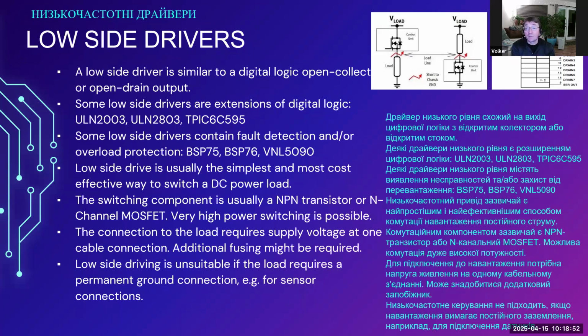This means that one end of the load is connected to the supply voltage. This might have effects on the cabling that you're using. I will talk about that. This is generally the easiest way of switching a load. Low side driving is not the intuitive kind of driving, but with the technology that we have, it is the easiest type of turning on or switching a load.